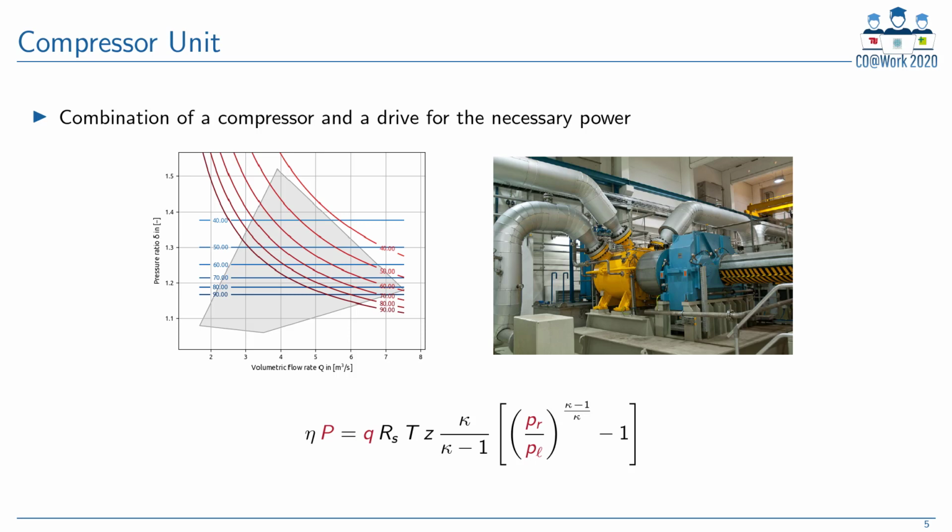The colored lines represent additional restrictions based on the pressure level of the gas going into the compressor. Those lines that are red denote the restriction imposed by the maximum power that the drive is able to deliver.